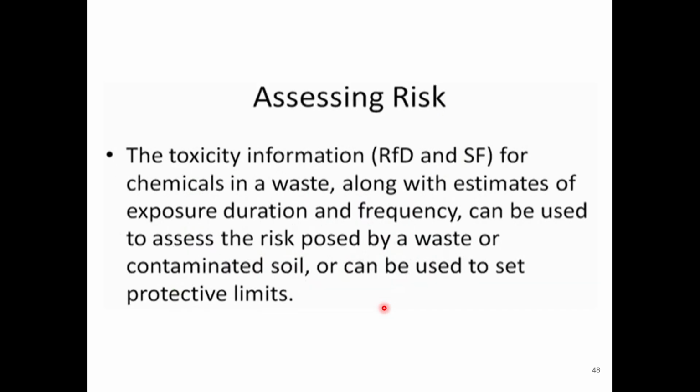So assessing the risk, basically the toxicity information, that is RfD, reference dose, and SF, slope factor, for chemicals in a waste, along with estimates of exposure duration and frequency, can be used to assess the risk posed by a waste or contaminated soil, or can be used to set protective limits. So these are some of the requirements which can be kept in mind. The information for chemicals along with estimates of exposure duration and frequency can be used for assessing the risk. So these are some of the data which can be used.